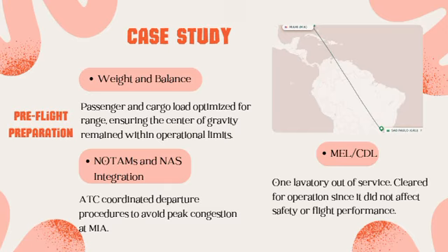The NOTAMs and NAS integration. We reviewed NOTAMs and revealed construction at GRU affecting taxiway usage. Additional temporary restricted airspace near MIA required a modified Standard Instrument Departure (SID). Coordination with ATC allowed for an optimized clearance, ensuring no delays during departure. So NOTAMs informed adjustments to departure and arrival procedures, avoiding operational disruptions.